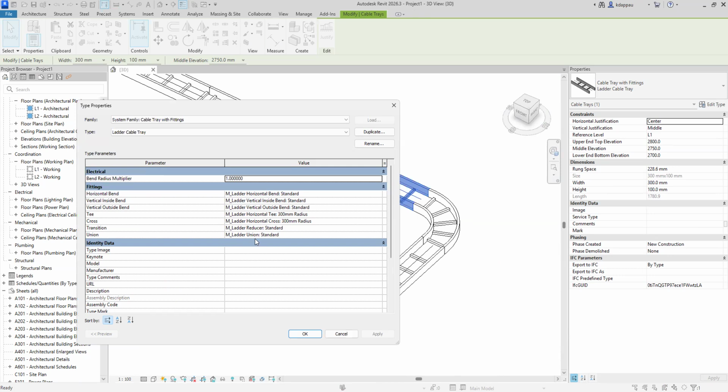In a future date, if you become a master Revit user, you might not even be using the default metric one, because they are very basic. There are industry standards. There are manufacturer specified fittings that you can load and then use, and not depend upon this one. So these ones you can use to do LOD 200 drawings.